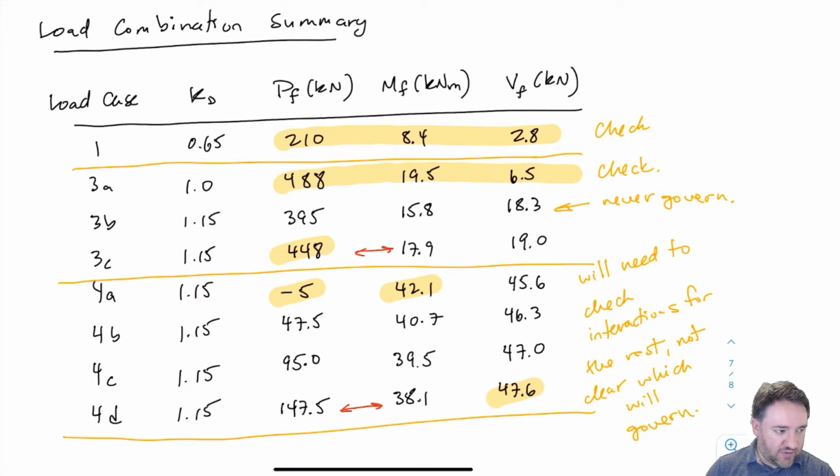So now that we have some more information, we are going to go ahead and try to, first of all, look at what the deflection criterion is, which is the only thing that we kind of haven't looked at yet. And also to go ahead and pick a trial section. And that will be the section that we go through and do all our full checks for moment, shear, compression, deflection, and then, of course, our beam column interaction. So let us get started.